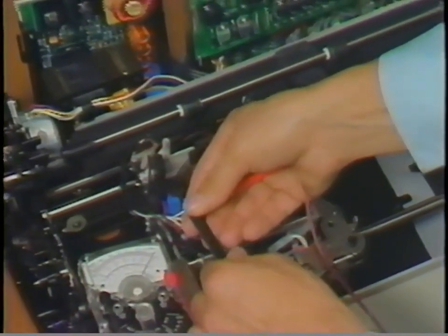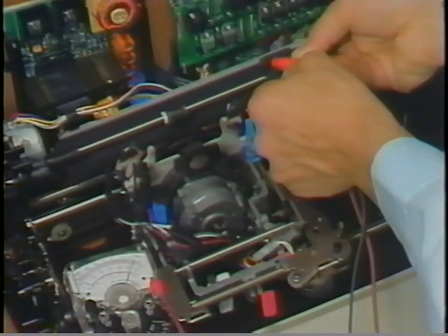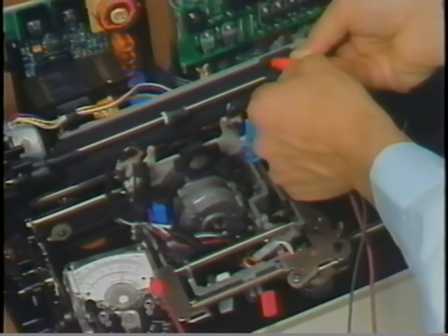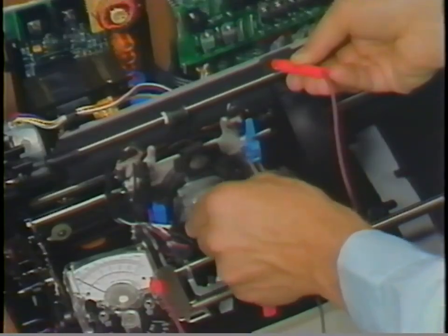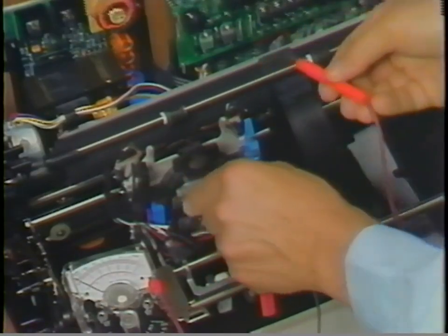When you have adjusted your meter, measure the hammer solenoid resistance from pin 1 to pin 2 on the carrier cable connector J4P. The hammer solenoid must read from 2 ohms to 4 ohms. Any reading higher than 4 ohms or lower than 2 ohms will indicate a defective solenoid. Next, check to be sure that there is no continuity between the solenoid housing and either pins 1 or 2 of the carrier connector.